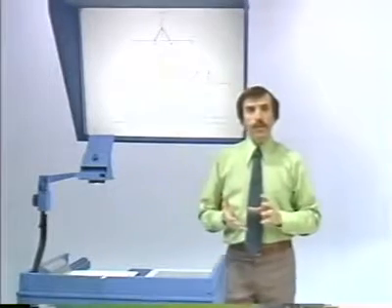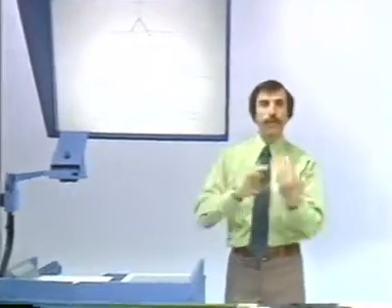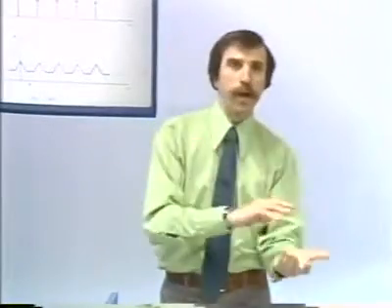So what happens here then is that, in effect, higher frequencies get folded down into lower frequencies. What would come out of the low-pass filter is the reflection of some higher frequencies into lower frequencies. As I suggested a minute ago, that effect is referred to as aliasing.